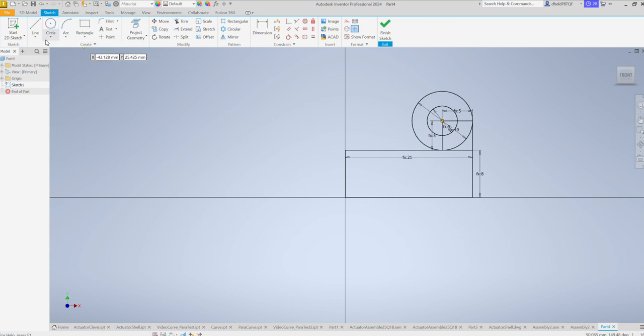Okay, now I'm going to create a line, and this line is going to go up X times 4. And now I'm going to have this line here that is tangent. So I can just click here, and now I can click on tangent, the line, the circle. Now it's tangent.